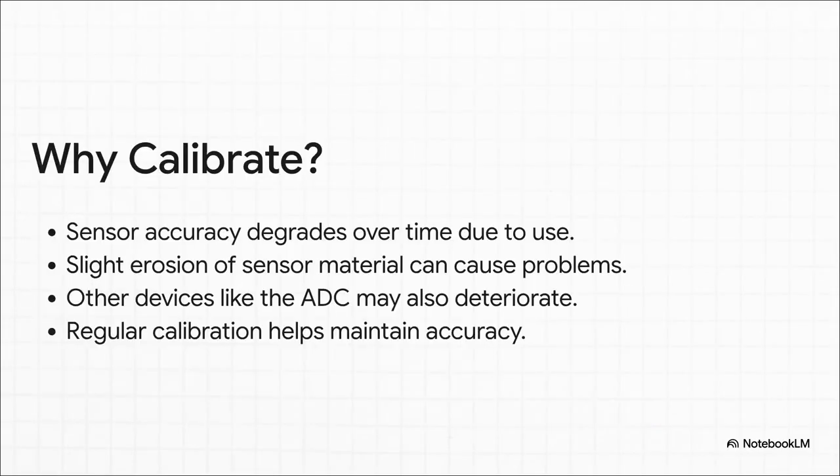And this isn't a one-and-done kind of thing. Just like any tool, sensors wear out over time. Physical parts can erode, the electronics can drift. It all leads to less accurate readings. So regular calibration isn't just a good idea, it's absolutely essential maintenance if you want trustworthy data.